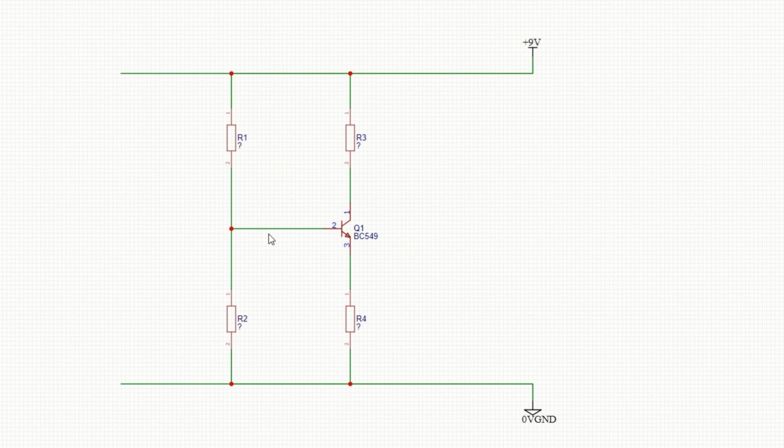then any change in the base voltage will cause a change in the voltage on the emitter resistor. Then the change in voltage across the emitter resistor will be reflected in the change in the voltage on the collector resistor, in proportion to the resistor values and the current through them. Now that might sound complex, but in fact it's very, very simple.